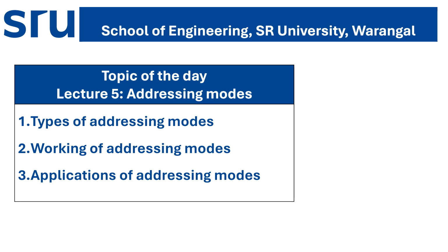MOV A, 25H or MOV A, R0 actually fetch data from memory or registers, right? We will also analyze how the microcontroller internally processes these instructions using registers, memory locations, and data paths.